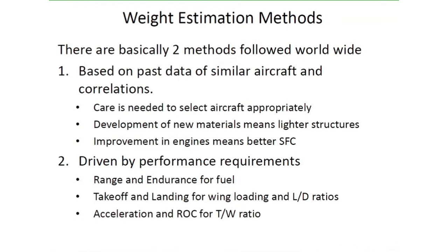This is one technique, one approach process, and we'll of course also use the other approach process, and that is driven by performance requirement. Any aircraft comes with either a requirement of range and endurance, and from this you can estimate the kind of fuel consumption you're having, takeoff and landing, and this will dictate the kind of wing loading and L by D ratios you are going to need.